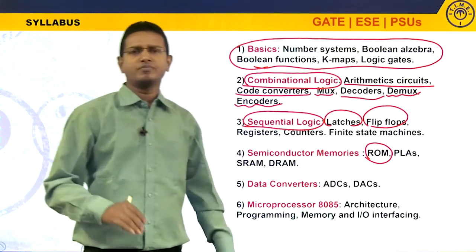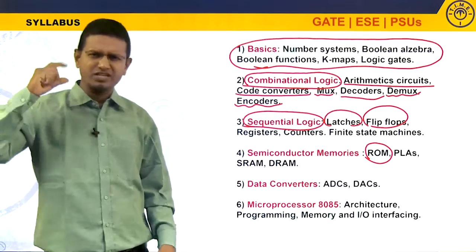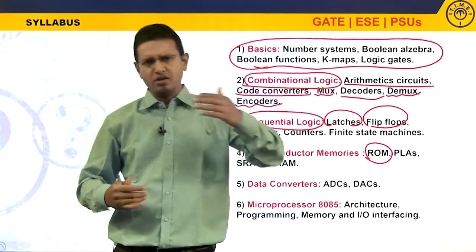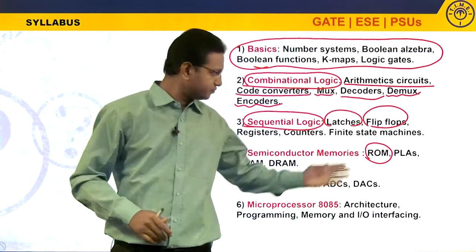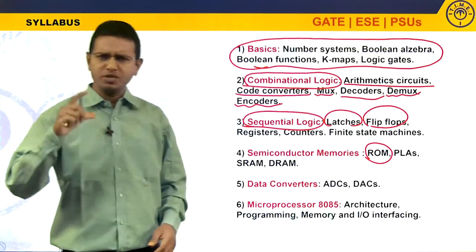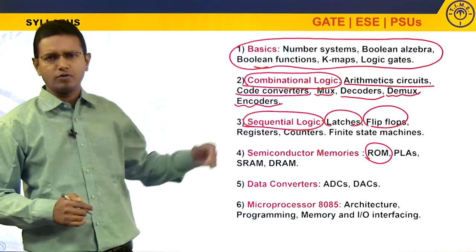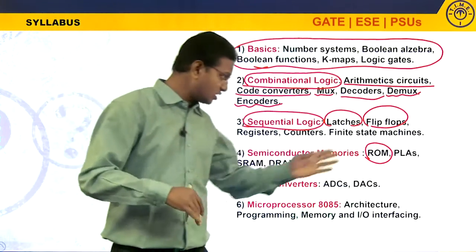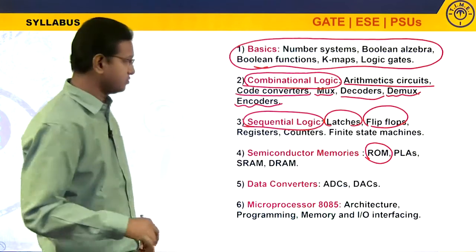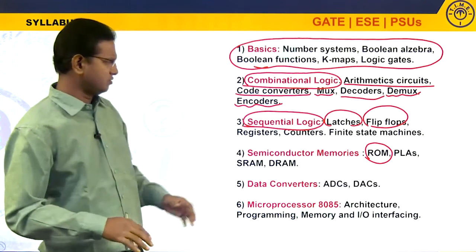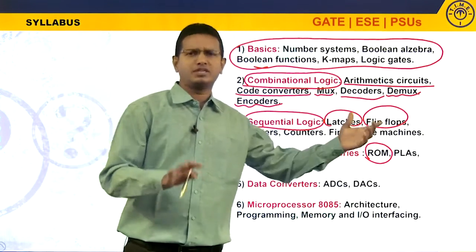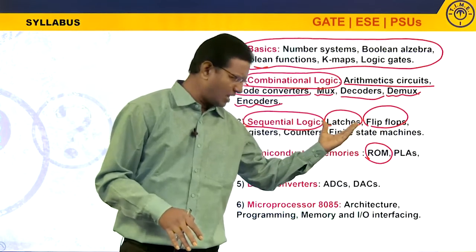Similarly, for flip-flops the output changes on the clock edge. If they work for the positive edge, they are called positive edge triggered flip-flops. If they work for the negative edge, they are called negative edge triggered flip-flops. However, the basic construction is the same, only the triggering is different.